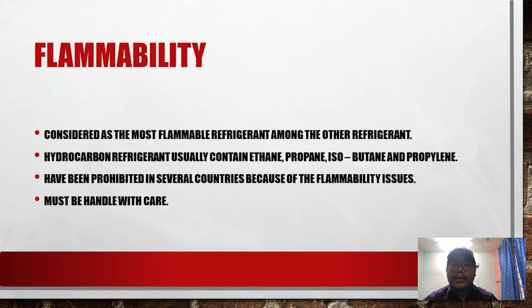Eventually, hydrocarbon refrigerants are 50% more efficient conductors of heat than fluorocarbon refrigerants, and their operating pressures are about 20% lower than that of fluorocarbon refrigerants. This lower operating discharge pressure reduces the work that the compressor has to do, thus reducing wear and tear.